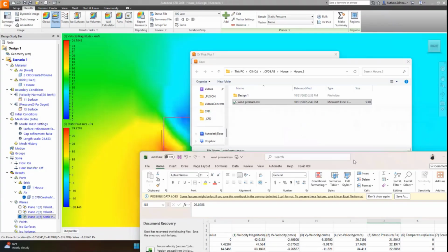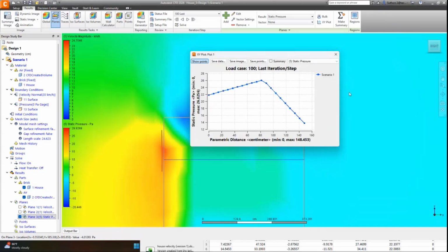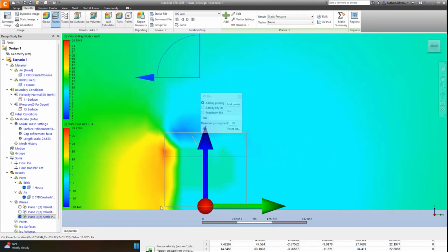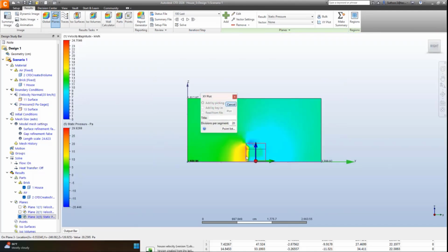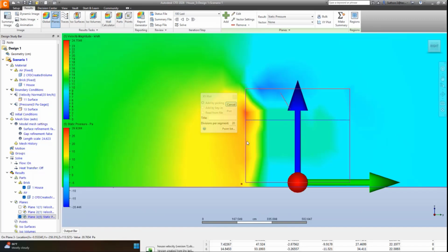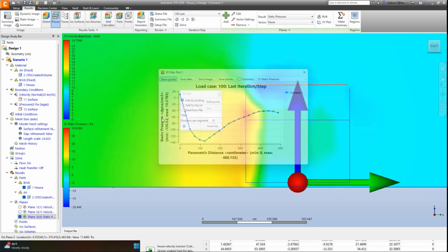But why is there no negative number? Because you cut, or you dragged the line, just in this portion. If you want to see all the pressure along this face, you have to use add point again, but you have to start from the bottom to the top. This area is just the positive pressure, right? This is the negative pressure that we add instead in this area. It's cut to the blue area, right? And then we plot.